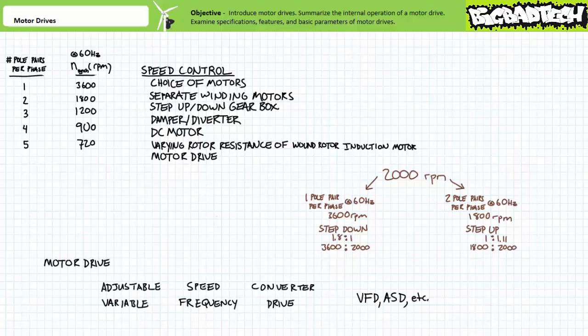Motor drives are known by many names. Pretty much pick one of these words, variable or adjustable, one of these words, frequency or speed, and one of these words, drive or converter, and then string them together in any order you want, and you've got something I'm calling a motor drive. Acceptable combinations include variable frequency drive, adjustable speed drive, or their numerous interchangeable abbreviations, VFDs, AFDs, VSDs, or ASDs. Regardless of the terminology employed, all of these devices are solid-state power electronics devices that, as some of the titles imply, vary or adjust the magnitude and frequency of applied voltage to a motor under its direction.